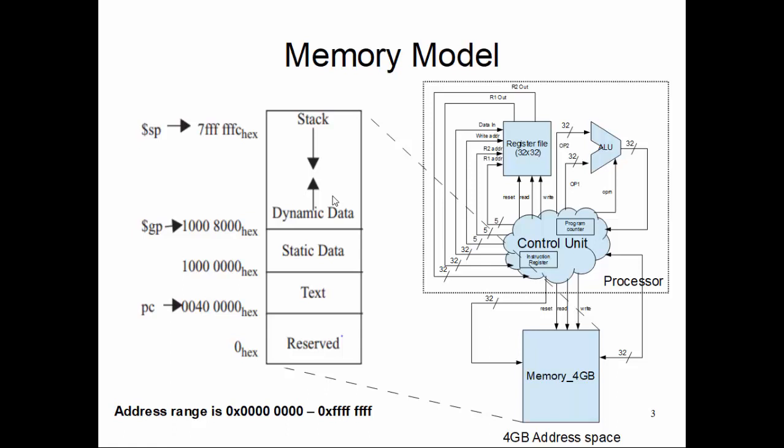And there is another concept called stack. Don't mix it up with the software stack, the data structure stack. Its operation is similar to that, but it is not that data structure we are talking about. It's an area which by convention is used as stack through push and pop kind of operations. Though push and pop is not part of native MIPS, we use the dynamic data stack part in that fashion, and it grows downwards, from higher address to lower address.